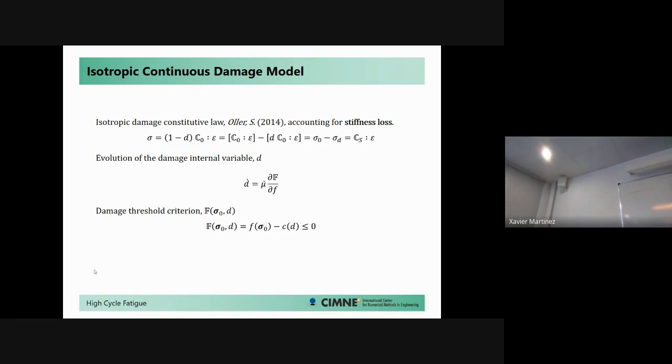Okay, now, in the damage threshold evolution function, I would say this term over here, what we are doing is we are quantifying how the nonlinear damage surface moves. And how does it move? Well, it can admit different types of behavior. For instance, you can have softening behavior or hardening behavior in a general way. In damage, we always have softening behavior. And the softening can be, for instance, linear, exponential. There are different mathematical equations that describe the evolution of this function, okay?